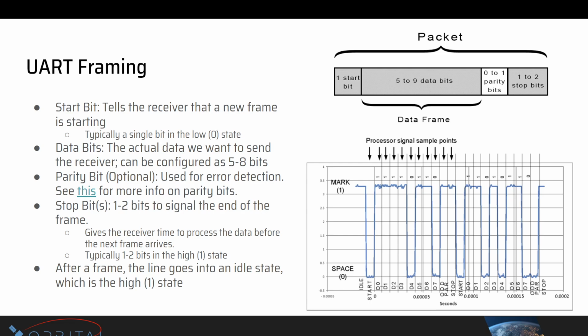Yeah. So in order to check for the start bit, do I need that? You wouldn't actually do that in software. That would be a hardware thing. I'd imagine there's some kind of exception or interrupt that gets triggered when it gets pulled low. The UART controller would be a separate little small device, not your MCU, that would know as soon as that line goes low, and it'll start sampling the bus for the next bits.